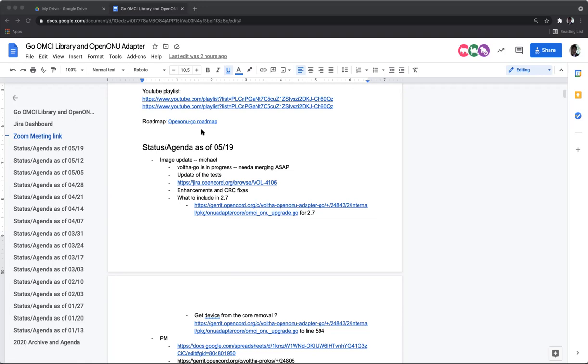Probably that ONU now reacts to the end software download in a specific manner, which might not be conformant to the OMCI specification, so that the OMCI lib has some issue decoding that frame. But we could not finally verify that, because it's a little bit tricky to get down to the real OMCI frame in this test.